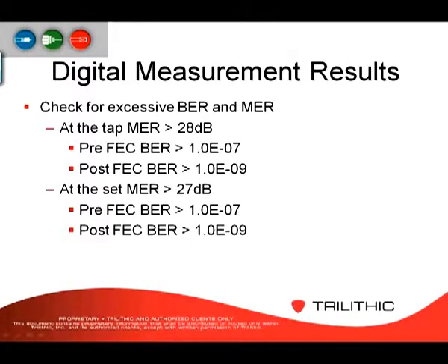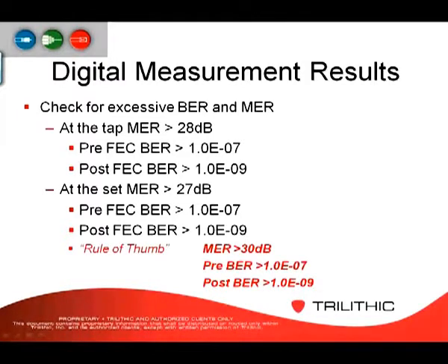So for your digital measurement results, these are some industry standards for what you're looking for as far as your MER and your BER. At the tap, you want greater than 28 dB. For your pre-BER, you want greater than 1.0 e to the -7.